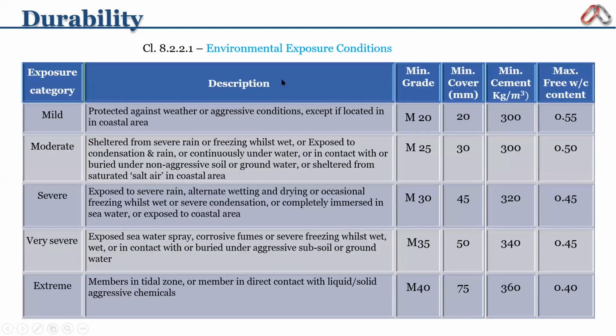So for minimum M20 grade of concrete, you have to use the minimum clear cover of 20, and the exposure category, depending upon the environmental exposure conditions, is mild in case of the M20 grade. It will protect against weather or aggressive conditions. Whatever the weather available in that particular region, it will protect your concrete from that.